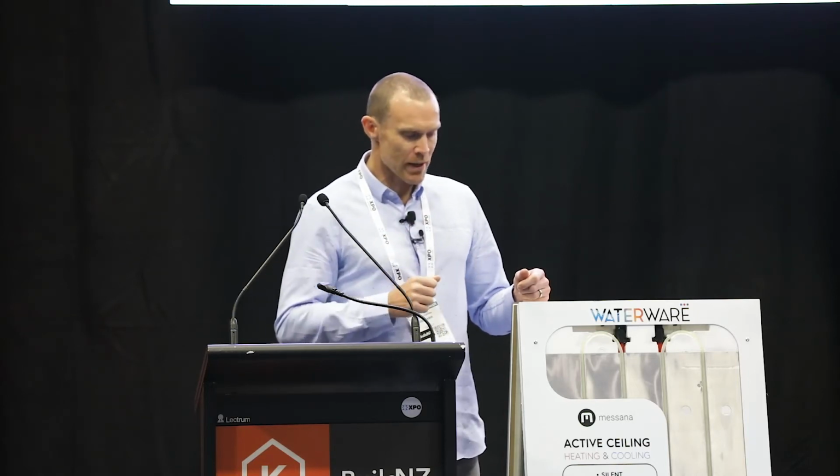So this system's very well matched to the new high efficiency appliances. Air to water heat pump, gas condensing boiler, it's a very good fit to those two appliances because they natively produce water in that sort of temperature range. An air to water heat pump operates 25 to 45 degrees, and a gas condensing boiler is the same, but you can go higher. It's a very good fit for a temperature compensation system.